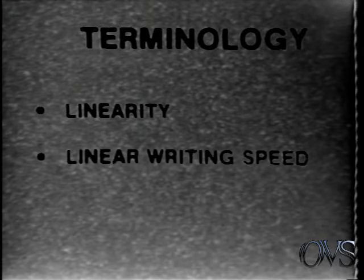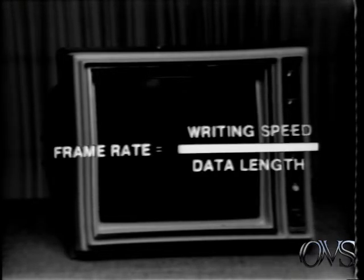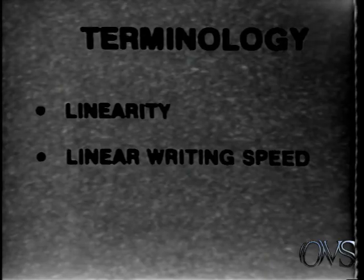Closely related to linearity is linear writing speed. This is the fastest speed at which a visible beam can be deflected across the CRT and still meet linearity specifications. The beam can be deflected at speeds much higher than the specified linear writing speed, but with degraded linearity. Linear writing speed determines the maximum amount of data that can be displayed without flicker.